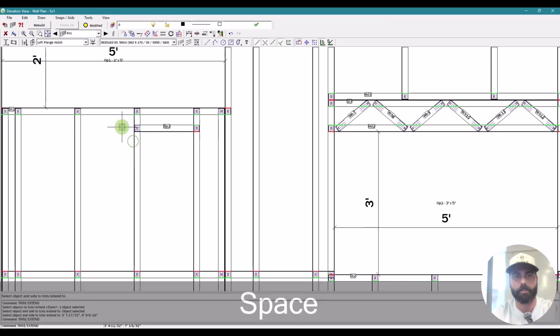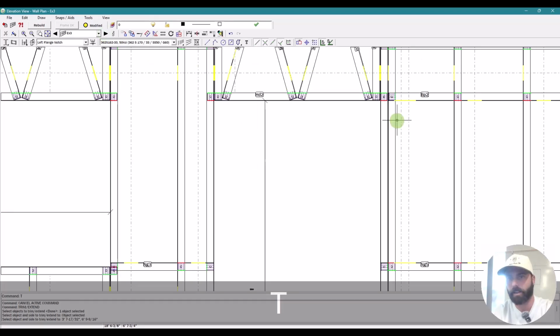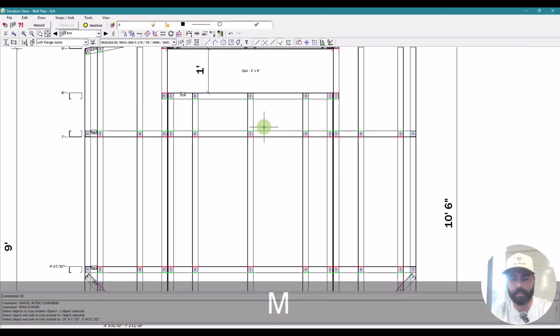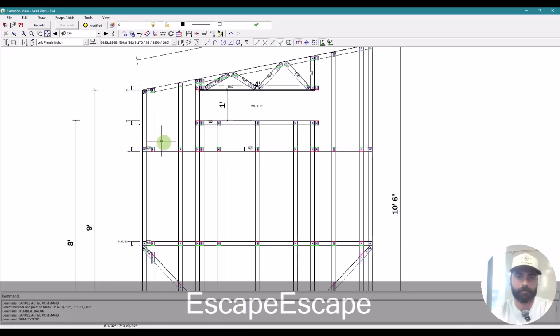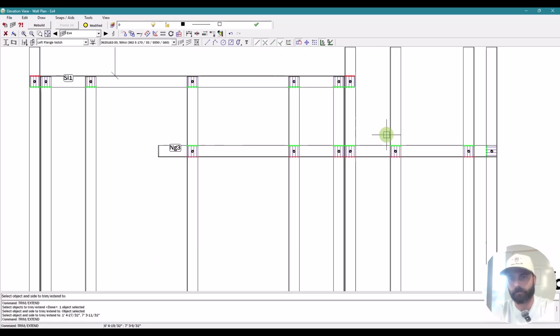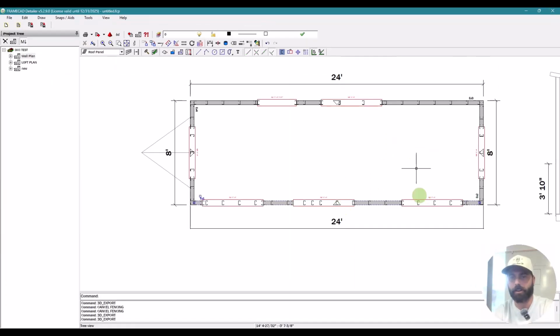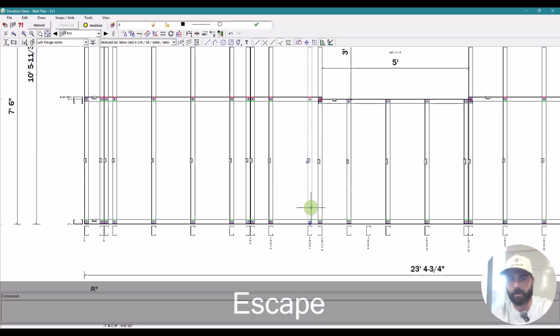Now, the only other thing that we could talk through is if we were to break this panel, how would I break this panel? So that's at 7, 8 3/8. So I might grab this stud and this stud at 16. I'm going to move them over 13/16 of an inch. That's so my sheathing still lands on a full stud at those panel breaks. Might grab that one too. And then you can go into the plan and you can do frame break. And I'll break those at that point.